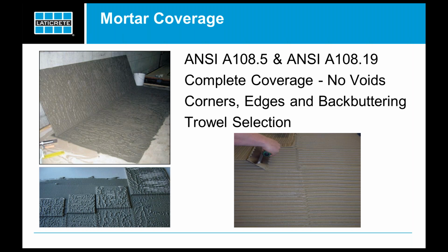For these large thin tiles, the standard outlines a different type of calculation for the coverage you want to get, and I'll try to cover it briefly. Basically, around the edge, the first 2 inches around the edges of these panels, you want to make sure there are absolutely no voids whatsoever. Then interior from there, in any single square foot, the minimum coverage is 85% in any given square foot on the inside of the 2-inch edge, if that makes sense.